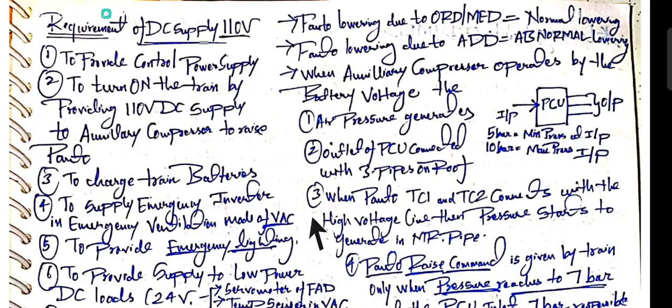Third supply which we have is 3 phase supply, but in this case voltage and frequency both are going to be variable. Like voltage is from 360 volt to 480 volt, and frequency is 40 to 60 hertz. So in this case voltage and frequency both are variable, and this variable voltage, variable frequency we are giving to compressors of the ventilation air conditioning system, or you can say compressors of the AC HVAC system, right?